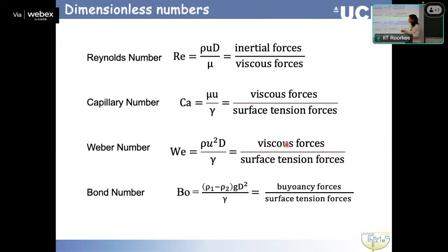And what I said here is that these are just general definitions. All these numbers are very well defined. Of course, when we have a single phase, it's very easy to say what is the Reynolds number. But when we start dealing with more than one phase, we have to define how exactly we calculate these numbers. Because we could have a Reynolds number based on one phase or on the other phase, based on the actual velocity or the superficial velocity or the mixture velocity. And the same applies with all those.